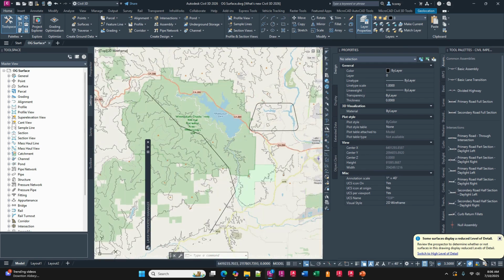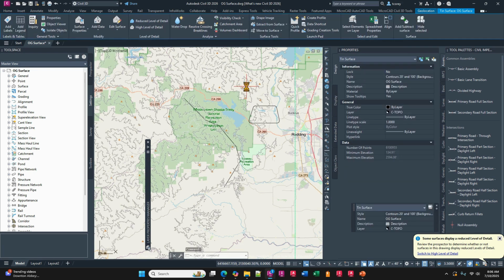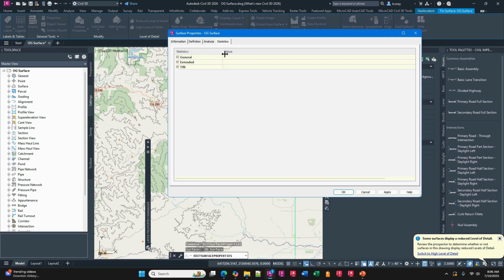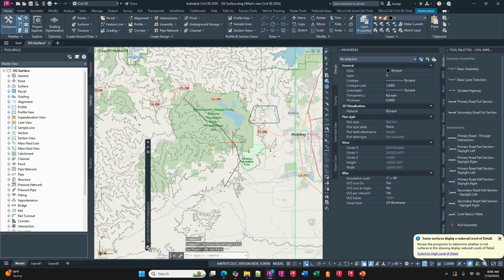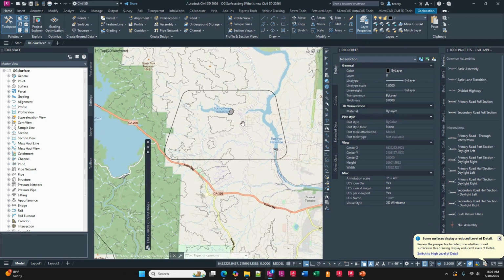It can be terrain data like I did here, which is a GeoTIFF, so it's a grid surface. But then I take and make a TIN surface and add that to the TIN surface, which I have. So it looks like there's 6,100,955 points in that surface. Well, that might be a bear to carry around when I'm just going to be working, instead of this whole big surface area, down in here near the Spring Creek Reservoir. So I want less surface.